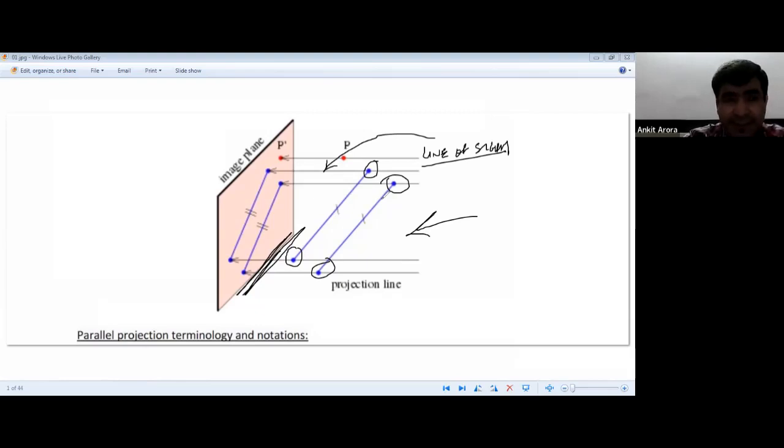It is one of the most basic tools in descriptive geometry. The projections are usually called orthographic, because they are orthogonal and parallel, and they are never going to meet, if the rays are perpendicular to the image plane. And if it is at an angle, or oblique, hence the name oblique, or skewed, SKEW. So you remember this also, they are sometimes referred to as skew, right? So this is how it is. These are the basic terms that you need to remember when you are talking about this topic.